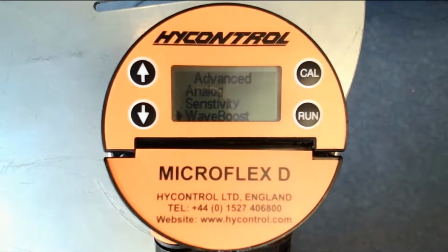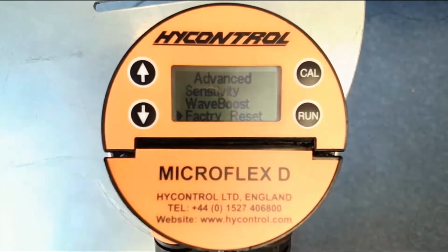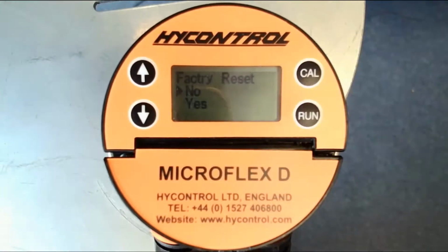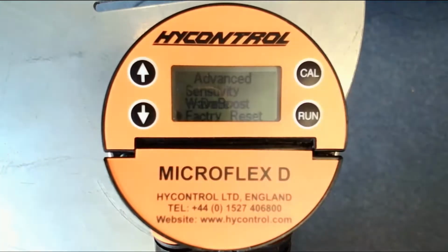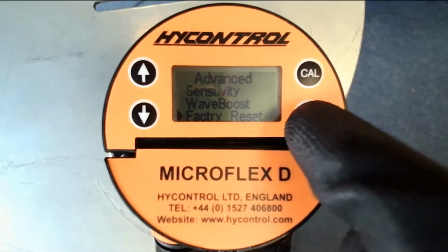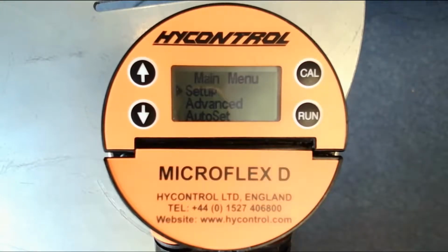Press the down arrow now to move to our factory reset. Press the Cal button once, and we can select yes now to reset the parameters to factory defaults, and press the Cal button, and we just get the question, do we really want to carry on with this? So we select yes and press the Cal button. So we can see that this is done, and now all of those changes we did make through the advanced setup have returned to default settings. So if we press the Run key, now we can jump back to the main menu and Run once more, and we see the distance at 900 millimeters, and we're at default setting in distance mode at the moment.